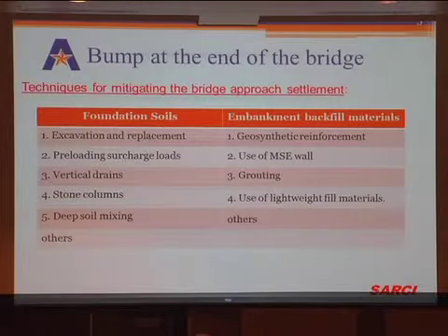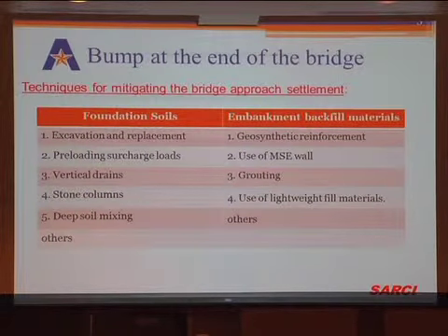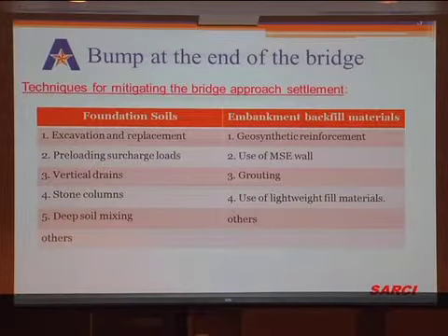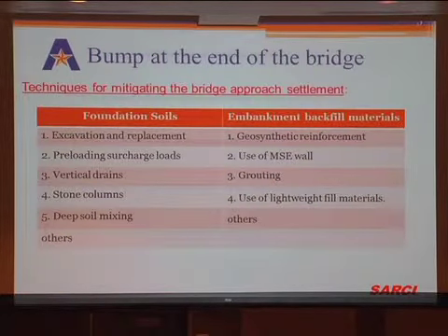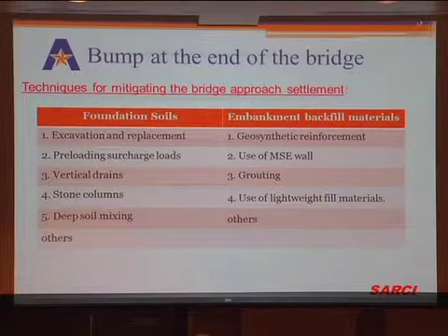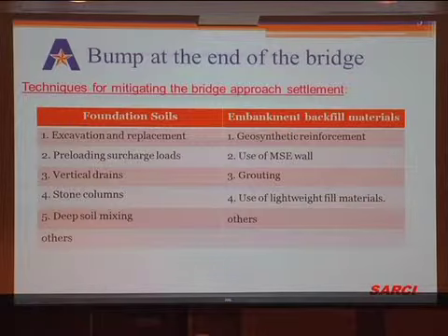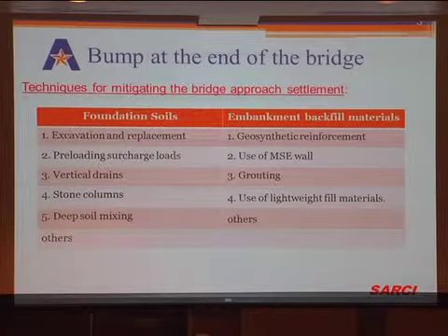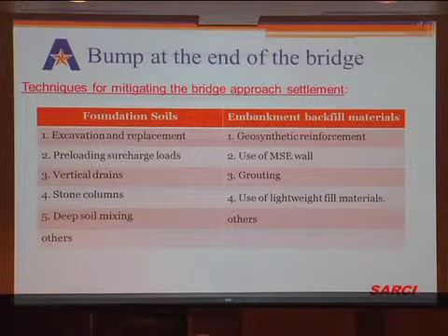Preloading with a surcharge load is done really if you have a soft clay. I'm talking about more like the Boston or San Francisco area where you do have embankments. They do have to preload them because the natural subfoundation soil is extremely soft and undergoes primary consolidation, so you have to load it with whatever load is going to come from your structure, preload it, and then let it consolidate fast, and then take out that material and put your structure on top. And then other things are vertical drains. You have stone columns, which is one of them, or sand columns you can use, and also prefabricated vertical drains, which are your PVDs.